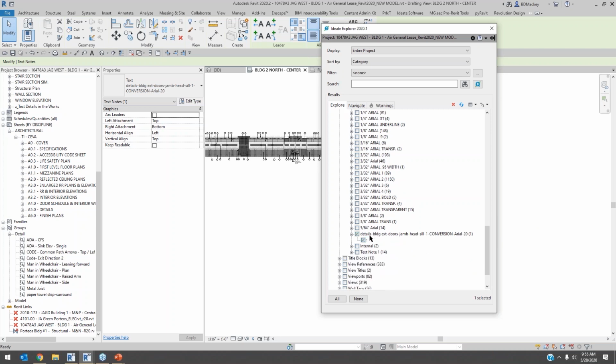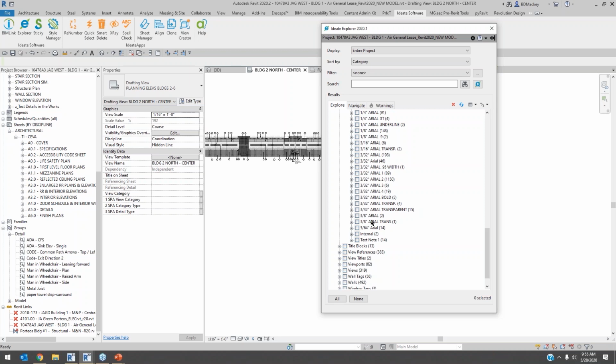So when I see something like this, oh, gee, there's a piece of text that probably came from an exploded DWG, and it's literally just a colon. Yeah, sorry, you're going bye-bye, delete. Right, so I'm just going to go in here and say delete, and now I've just gotten rid of that piece of text out of here. The text style still remains. I'm going to have to purge that out, but I did get rid of that one piece of text that was using it, keeping me from purging it out when I'm trying to find it, etc.